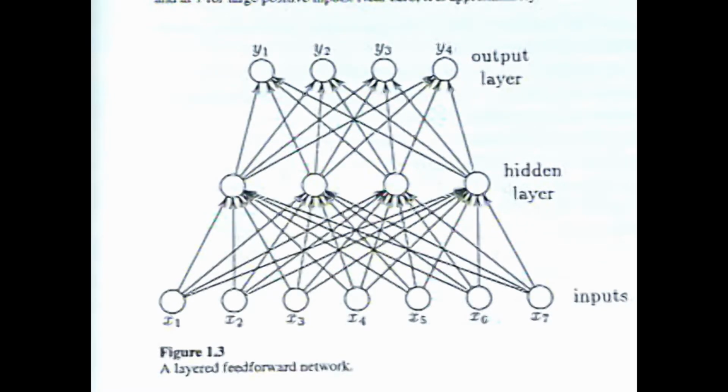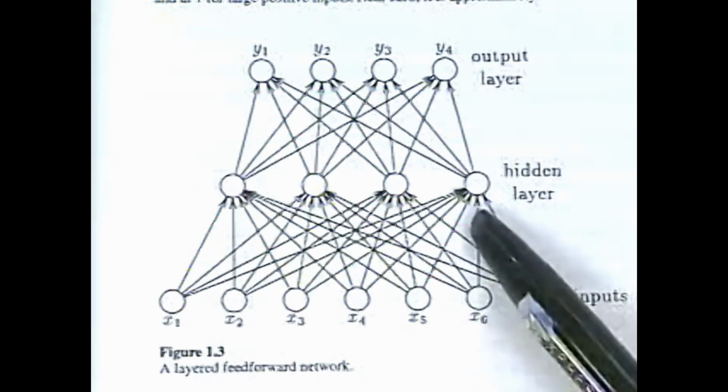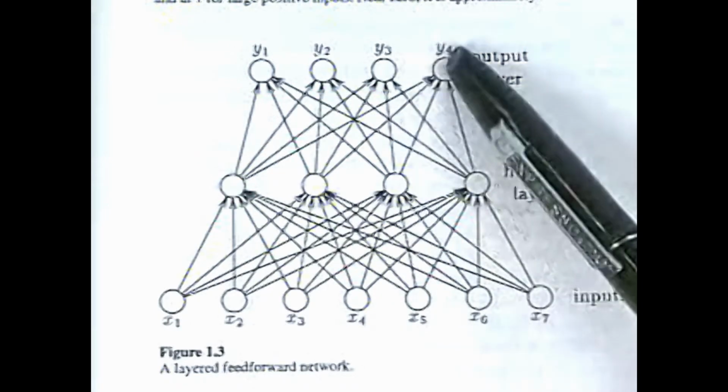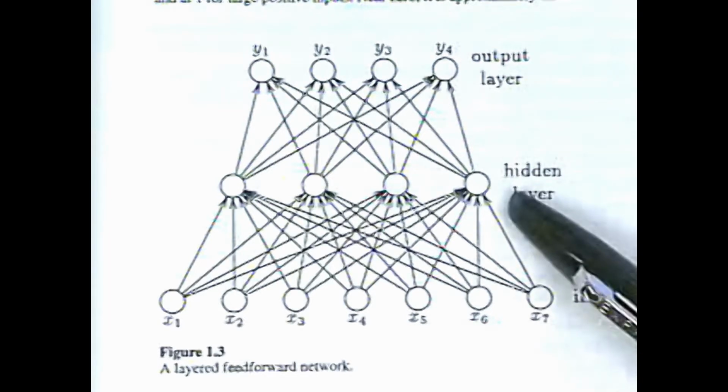And one of the reasons that we like feed-forward neural networks, for the same reason we like FIR filters, is we don't have to worry about stability issues, right? All FIR filters are stable, and so we can be assured that all feed-forward networks are also stable. If you have feedback, you can get into some very tricky situations, especially when you have feedback with nonlinearities. That's the classic model of chaos, for example, and if one isn't careful, one can break into a chaotic sort of situation in neural networks also.